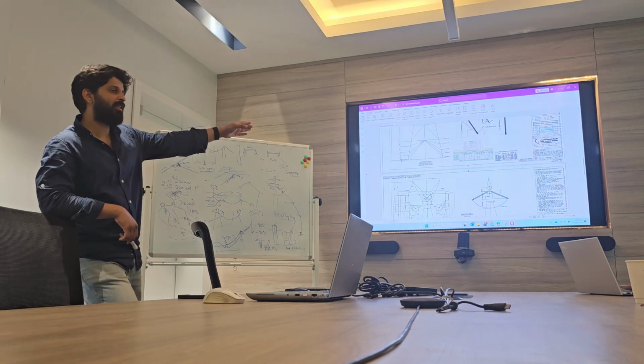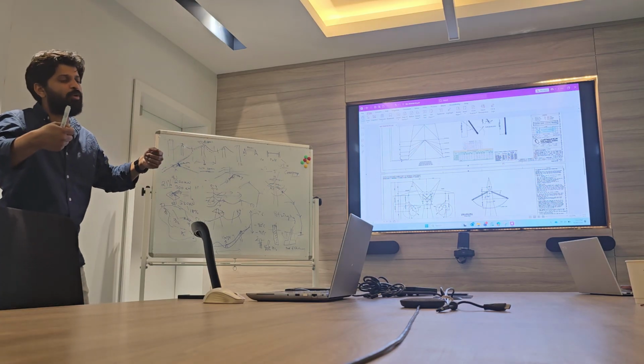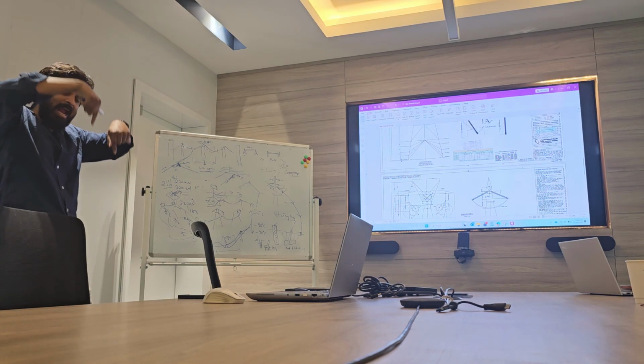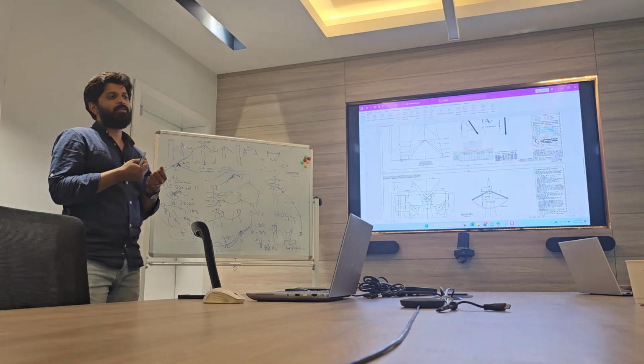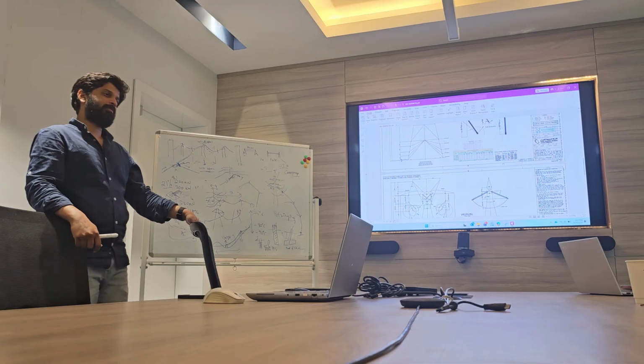That's the difference between a tension tower and a dead end tower. A tension tower is designed for both side tension loading. A dead end tower is designed for both side tension loading and one side tension loading. So it has the ability to withstand if something happens. Yes. It will still hold.